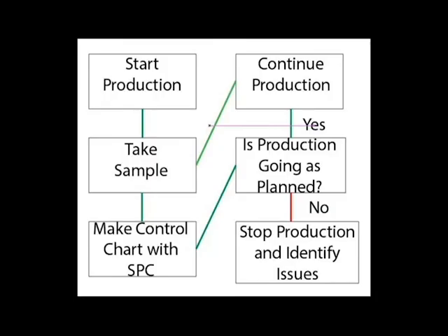Another reason why SPC is so useful is because it is cyclical. Samples are taken during the process and then plotted in a control chart, for example. If the engineers are content with the data, the process will continue. If they aren't, then the process is stopped, adjusted, and then run again until the engineers are satisfied.